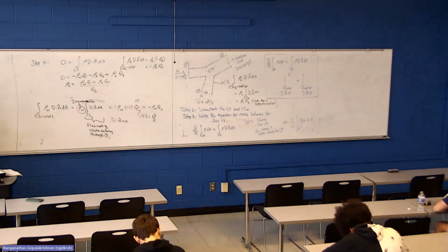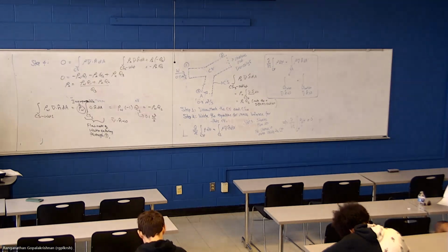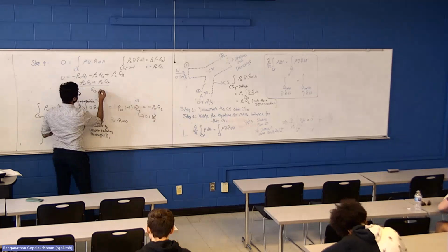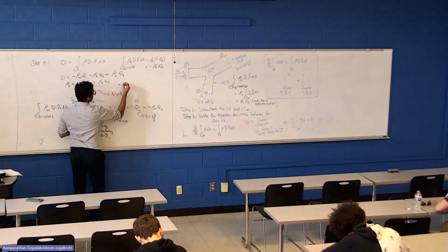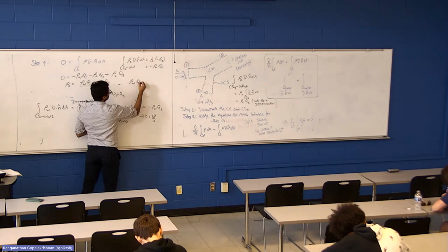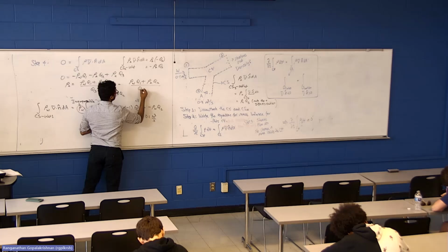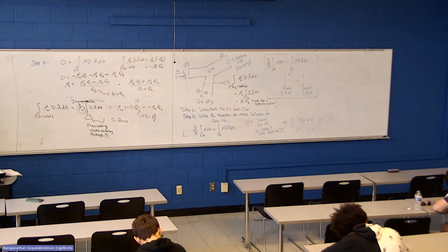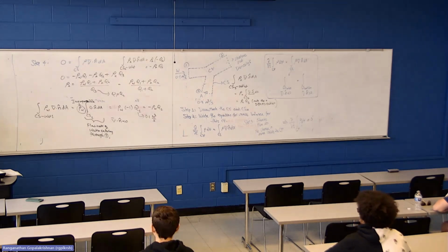What is Q3? How do we get Q3? Add the two together. We are mixing two volumes, right? That's the net volume. So Q3 is Q1 plus Q2. So this is like a weighted average where you have rho water Q1 plus rho alcohol Q2 divided by Q1 plus Q2. So that's your effective density of the alcohol water mixture stream that's exiting the Y duct.